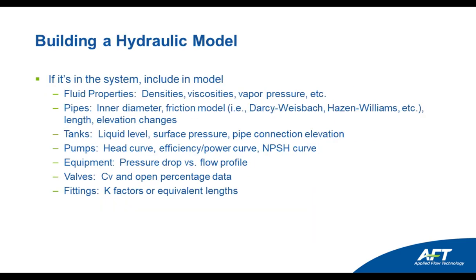Now, getting into the flow analysis aspect of things, what is important when you are trying to build a hydraulic flow model of a piping system? Well, the moral of the story is the more accurately and close to reality that you model your system, the more likely it is for model results to match measured data. And so if it's in the system, you should definitely include it in the model.